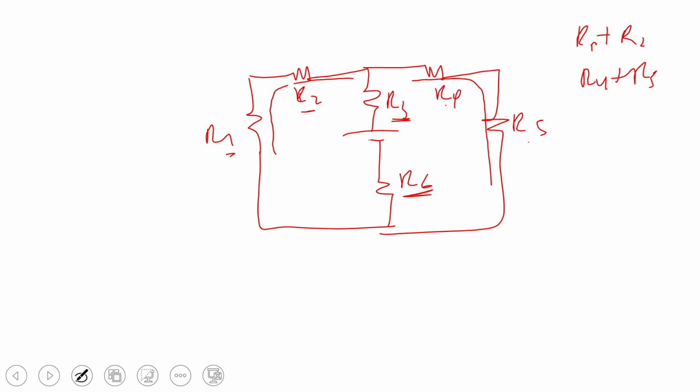We said the same current will pass through, and most students worry because the current that leaves the positive terminal, when it gets to this junction, some will come here, some will come here, and then they come together and come out like this. So you realize that the current that passes through R3, the same one passes through R6.